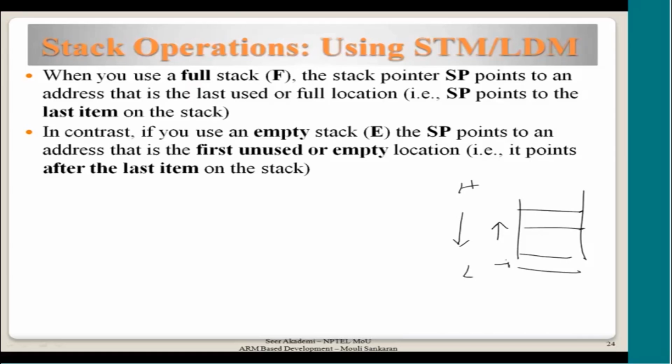Similarly, you have another choice of which register to use as the stack pointer. R13 is the default, but you could use any register to perform the same thing. If SP is looking at filled data, then before pushing any data, suppose you are using increment, you will do increment before, because it is already pointing at a full location.